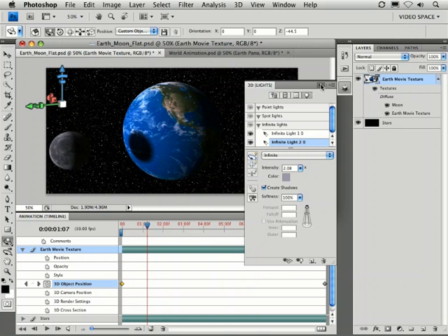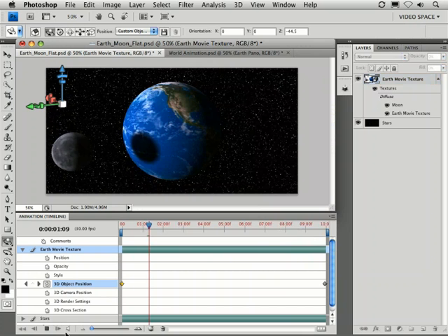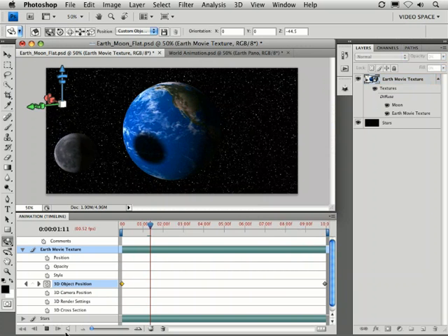Let's close this down. We would then go through and double check all of our settings here for our keyframes, but in general we can hit our spacebar and we can start to see this process, these different frames one by one. Now, because I have ray tracing on, the processing is very, very slow. As I said, if you're trying to get your keyframes to accurately position things, turn off ray tracing until you are ready to start to render your final image.